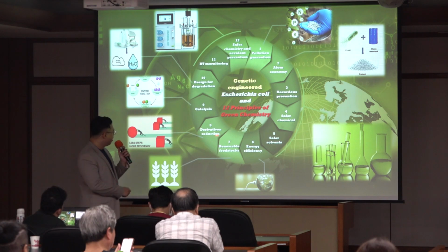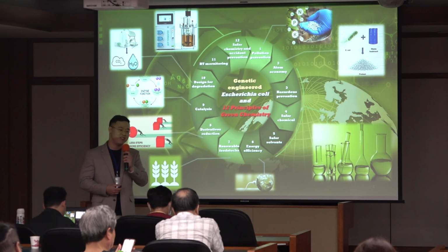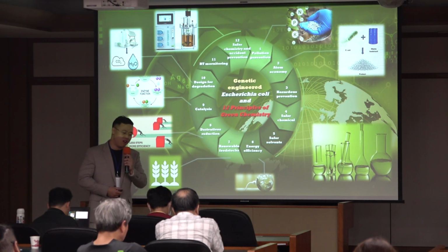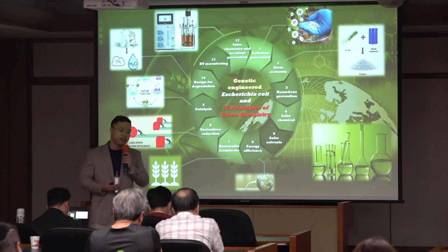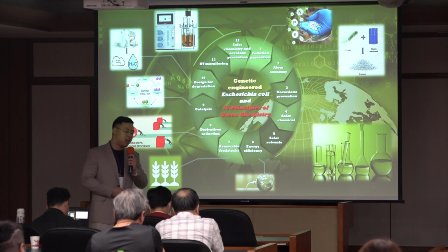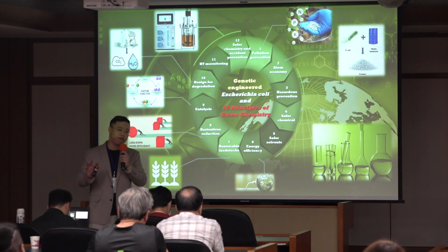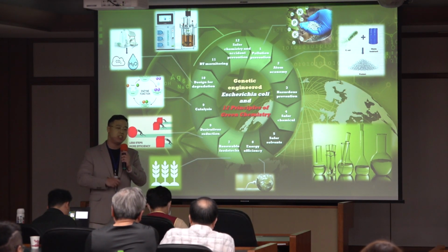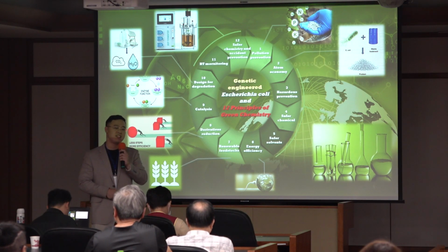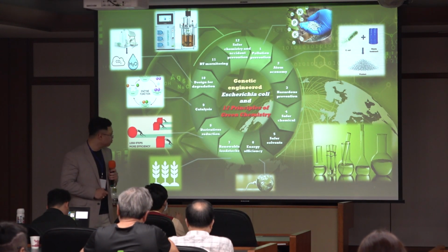For number 7, renewable feedstocks. As I just said, we use crude glycerol, which we can say is renewable. Or if you don't want to use some waste feedstock like that, we can always use something that we can grow. Right now, to produce PLA, NatureWorks has a whole farm of sugar cane. They use that sugar to feed their bacteria so they can produce lactic acid as the precursor for the bioplastic PLA, polylactic acid.